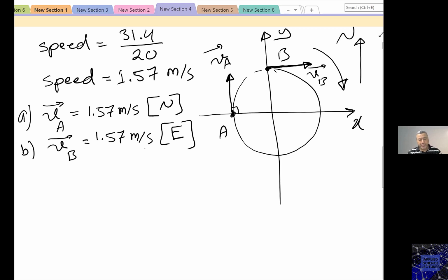This is extremely important to know. How did we calculate the velocity right at those points? Based on the understanding that the direction of the velocity is in the motion direction, and at the same time tangential to the circle, or to the path of the displacement. Any questions? No questions? Okay, so we found A and B.